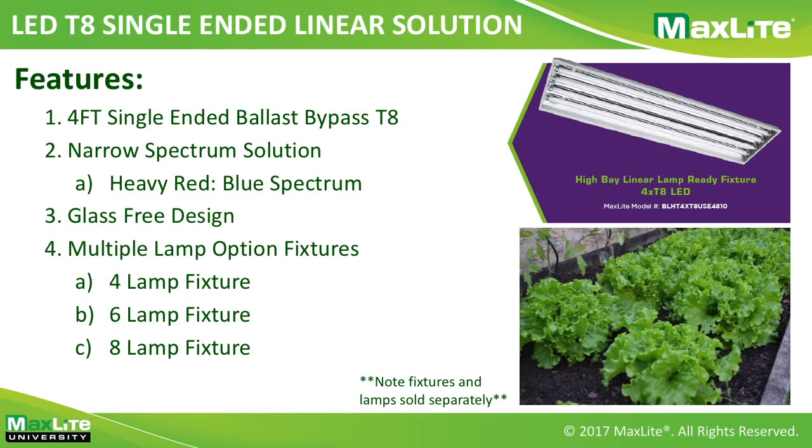It does have, as I described earlier, more of that scalpel, more of that very efficient, safe spectrum where it's providing just the red and the blue, so that as we look at more of the specs on the T8 single-ended linear solution, we do have various fixtures where we can put it into a 4-foot single-ended ballast bypass T8 type of setup, but also in multiple lamp configurations. So whether it's a 4-lamp, 6-lamp, or 8-lamp, we can meet that target intensity, say, PPFD that we're looking for. Typically, you'll use your T8 type of setup in the clone, seedling, and vegetative stages of growth, mainly because it offers a certain level of intensity of light.